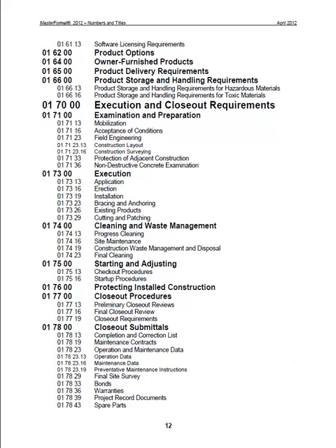We require as-built drawings and also a manual of operation. So anything that you've put into the building that has a warranty, that has maintenance items associated with it, we want everything documented and a full book of as-builts and operations and maintenance manuals for the construction after the fact.